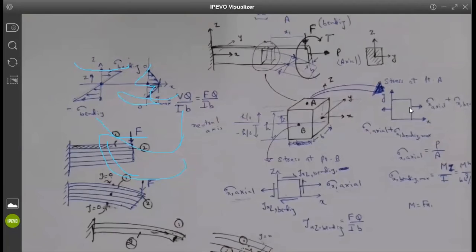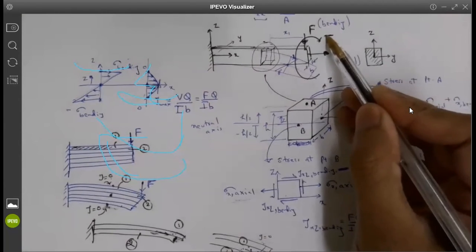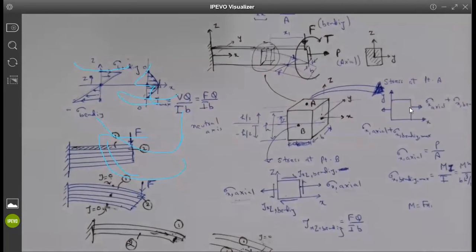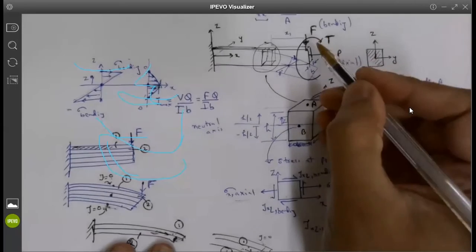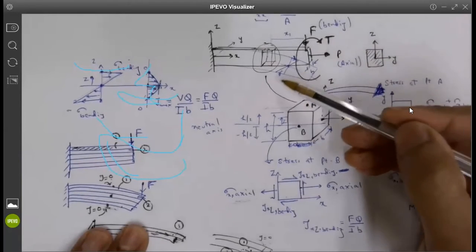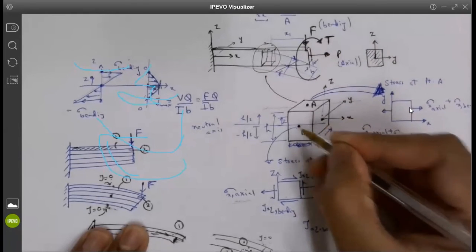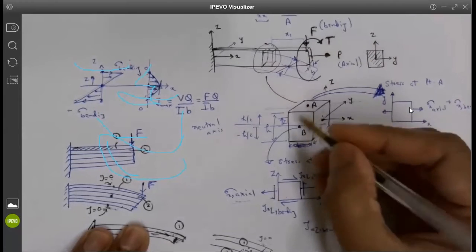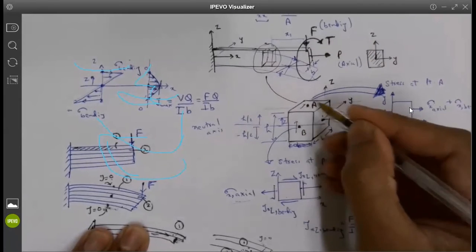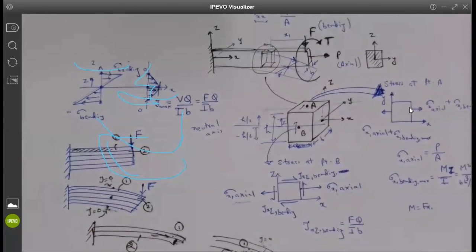Juliana. So Juliana, can you help us say what would happen if we have a twisting load in a material? What type of stresses will come? Is it normal stresses or shear stresses? It'd be shear stresses. Perfect. So that's what we have for a twisting load. When we have twisting, we only have shear stresses, and they will go through all the material. If I have point B, the shear stresses will act like that, then this, and so on. So everywhere the shear stresses will appear due to torsion, right, Juliana?